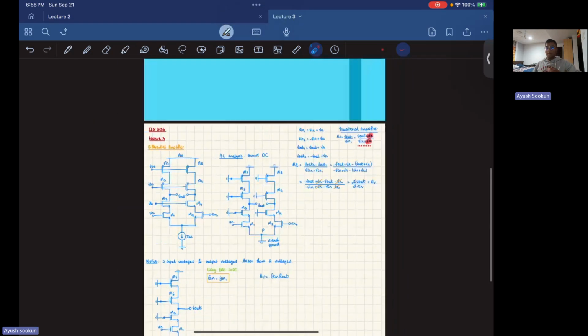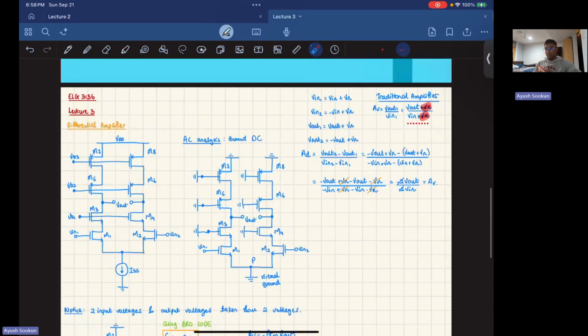So key takeaways from this video: understand the point of the differential amplifier, understand that it gets rid of the noise, and look at the proof to convince yourself that it got rid of the noise. If you want to measure the heart rate of someone, like in a hospital, you can't afford to have big noise, because the signal your heart sends for you to detect is so small that the noise might be bigger than the actual pulses from your heart.